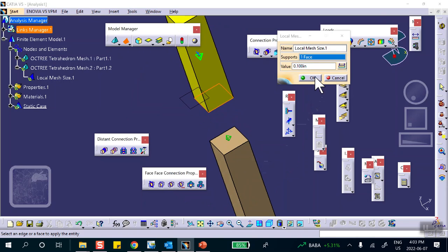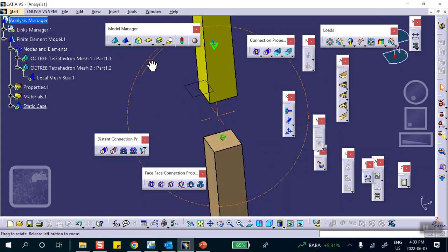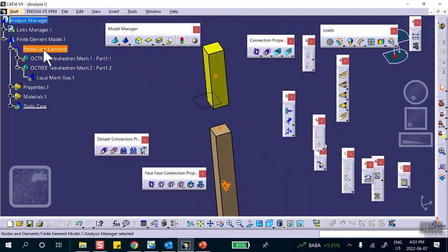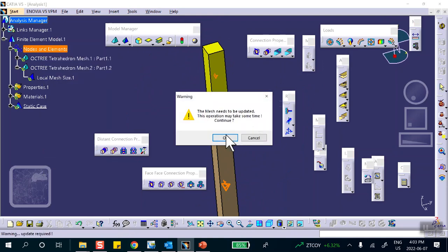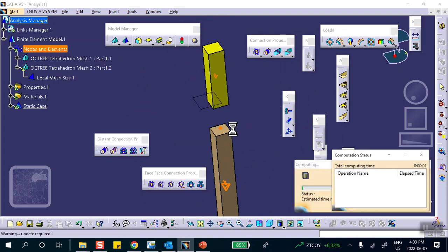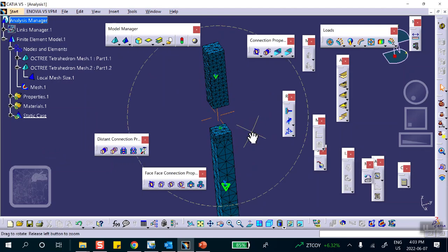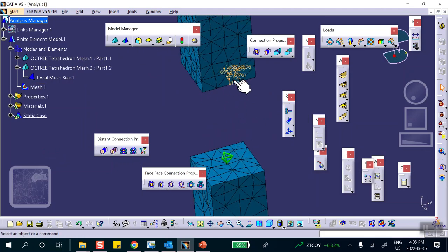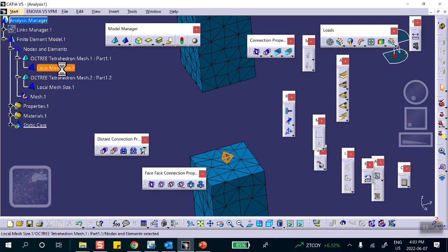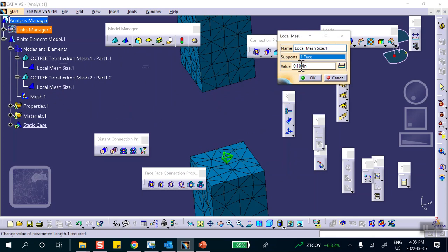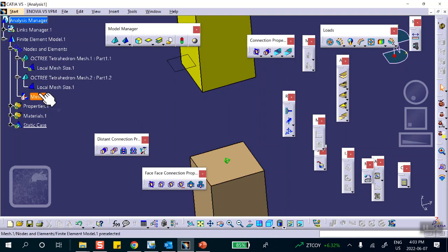That's okay. All right. So if you look at your mesh, right-click mesh visualization, it's going to be a little bit finer for both of them at the top and the bottom surfaces. Although here you can't really see it, but there, of course, you can. As a matter of fact, to be able to see this thing, I can make this even smaller. I'll make it 0.05. Okay, and now do it again.